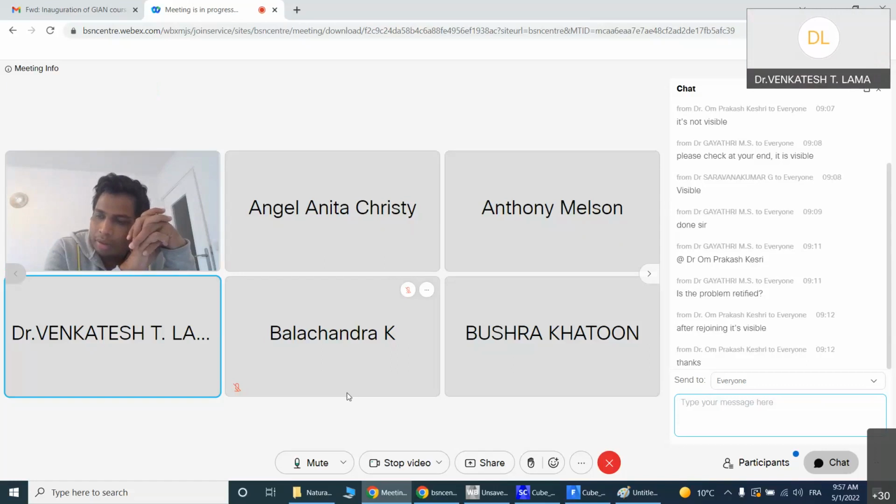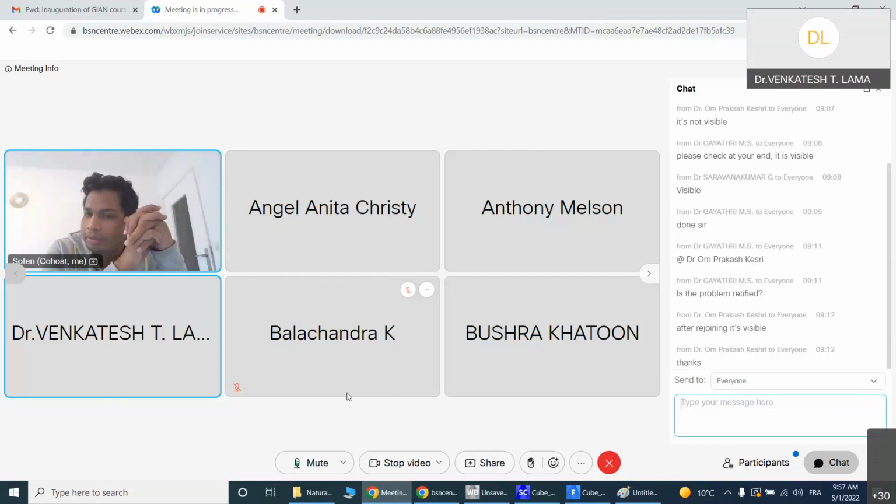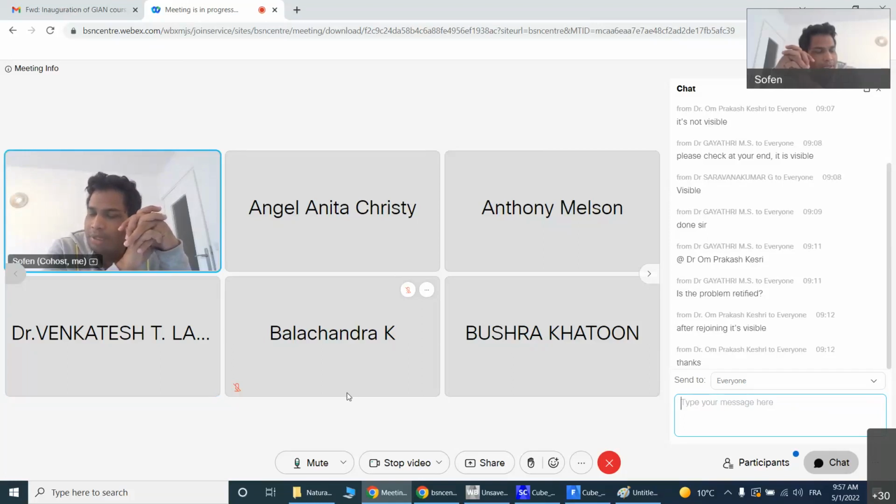for a sector. 0.5 million. Yes, sir. For a cylinder we chose a sector for in-cylinder combustion, and it takes at least 3 days. It depends upon how much time step size you are taking. If you take a very large time step, it will be computationally very fast, but your numerical stability may become an issue.